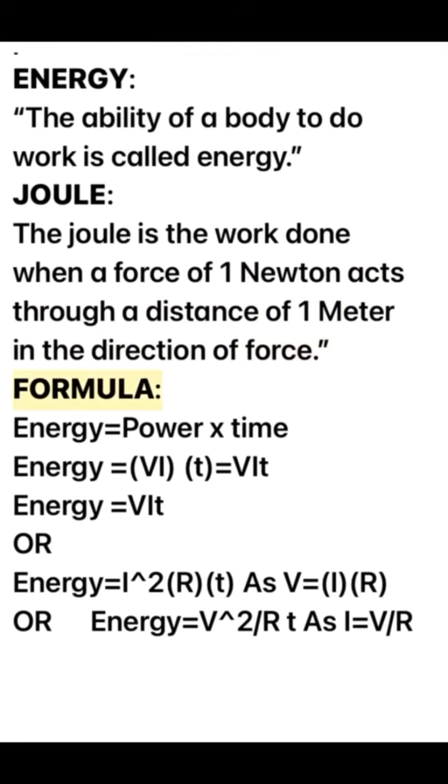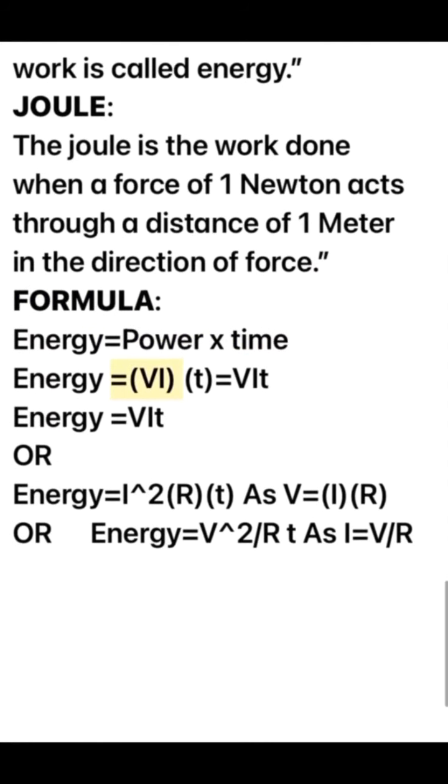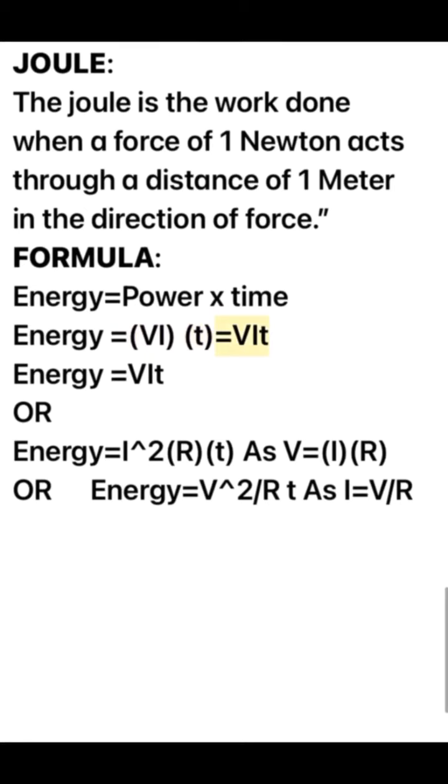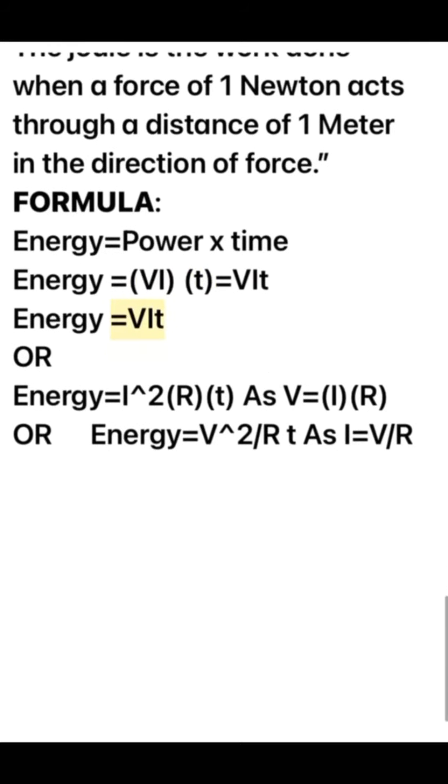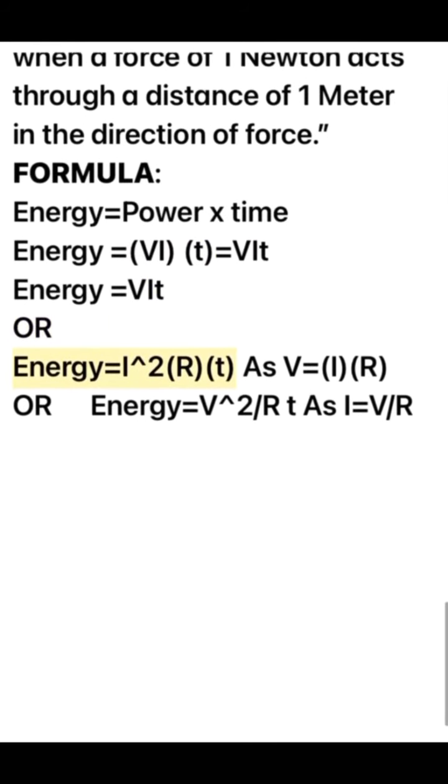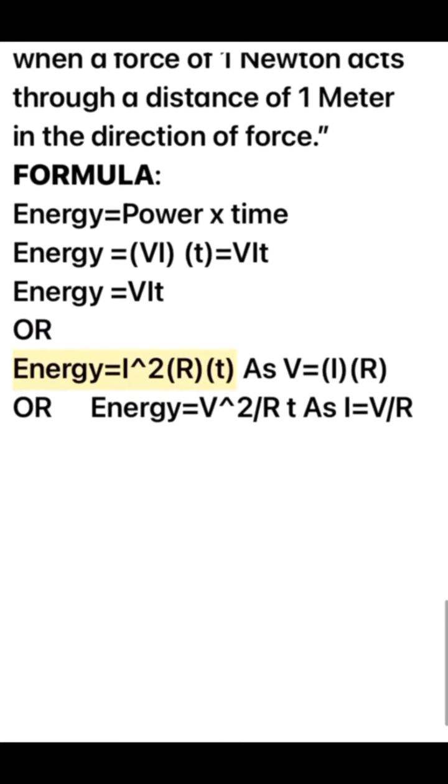Formula: energy equals power times time. Energy equals VIt, or energy equals I²Rt as V equals IR, or energy equals V²/R times t as I equals V/R.